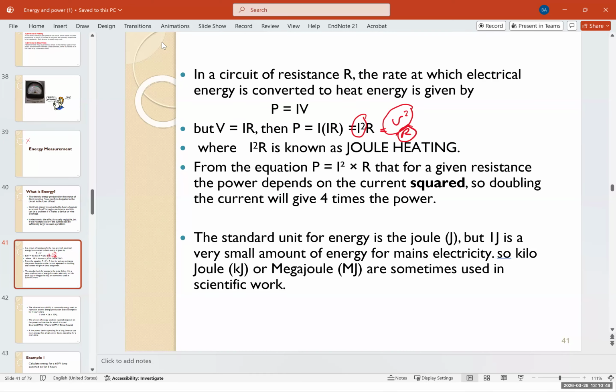And the main reason is, again, when you have a transformer, you can easily change the voltage and the current, and increasing the voltage has huge benefits. It reduces what they call the Joule heating, or the heating in the wires. When the wires heat up, we have an effect called the sagging effect, meaning the wire would become a little soft and sag, and they could have a short circuit, connect to a tree or something, and it's going to be disastrous.